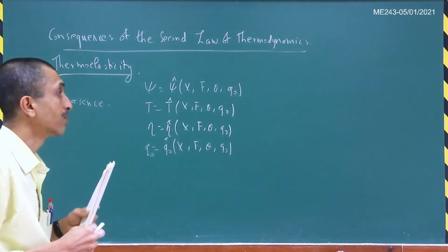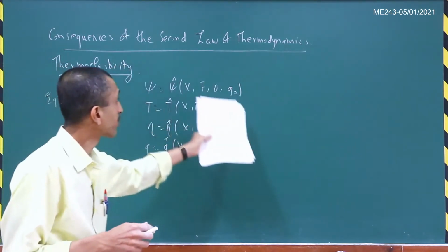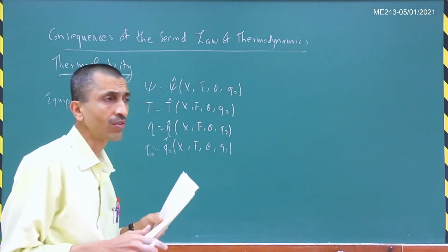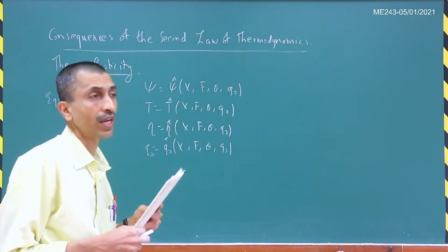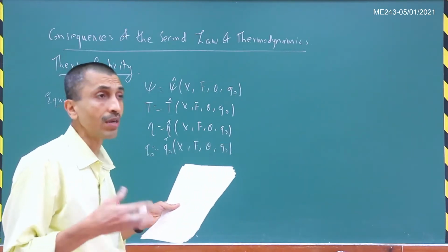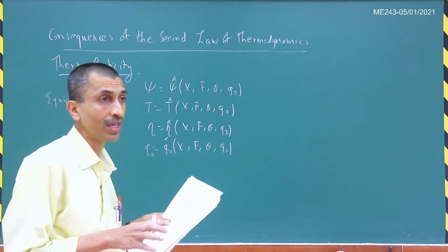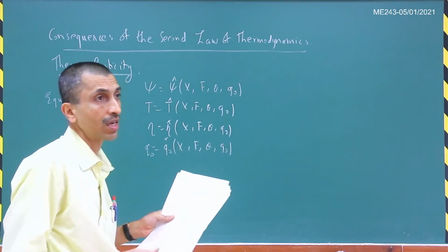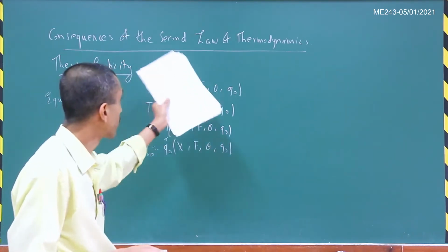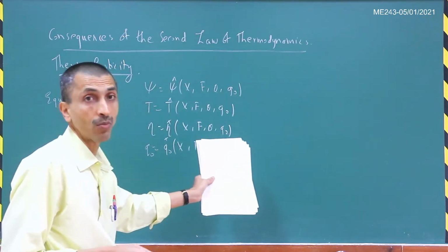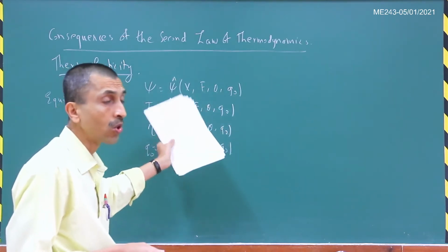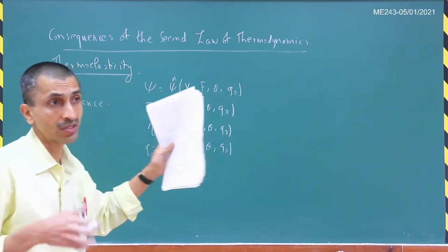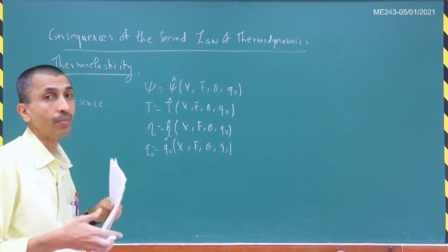And so this whole procedure is quite successful in finding out the restrictions on the constitutive relations in these two cases that we are studying. But as I've already mentioned, the moment you go to more complicated situations, applying this procedure becomes more and more difficult, because we do not know exactly which kinematical variables the stress or the entropy should depend on.